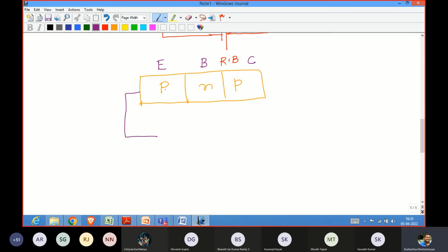Now we are getting this as forward bias. So P type is there. If I need to make it forward bias, I'll make this arrangement, because this is my plus, this is my minus. So plus will repel the majority carriers over here, hence the holes will move towards the right hand side. I'm just drawing it, although it is not needed, but this will be the first part.